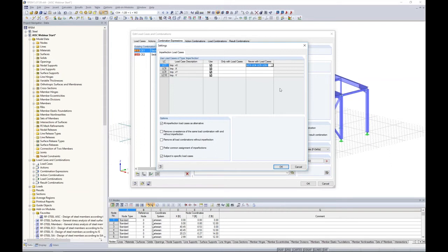If I press the down key, just like what we would do in Excel, and a quick trick, if I hit the F8 key, it will actually copy the entries from the cell above. So I don't need to necessarily go in and redefine these in that additional dialog box.